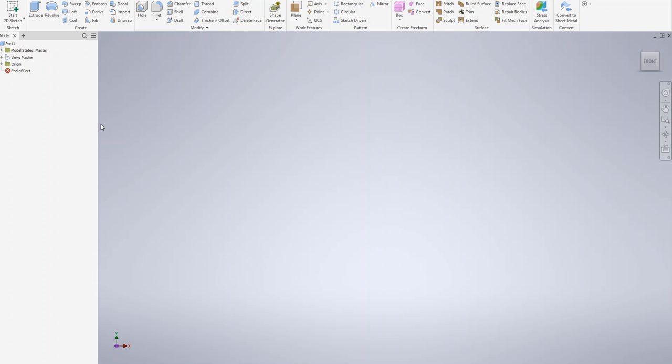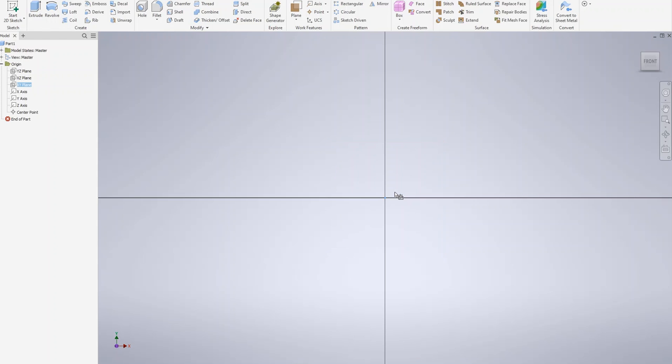You already know Inventor. You need to select the plane first. You're going to find the plane of your choice under the origin. Click on the plus button next to origin. It opens all the folders inside, and you choose the XY plane for the pedestal. It's good for the pedestal, so we click on the XY plane, and a blue area appears at the center of your screen. There is an icon. If you move your cursor on it, the label, create sketch, will appear. Click on that icon to create a sketch.